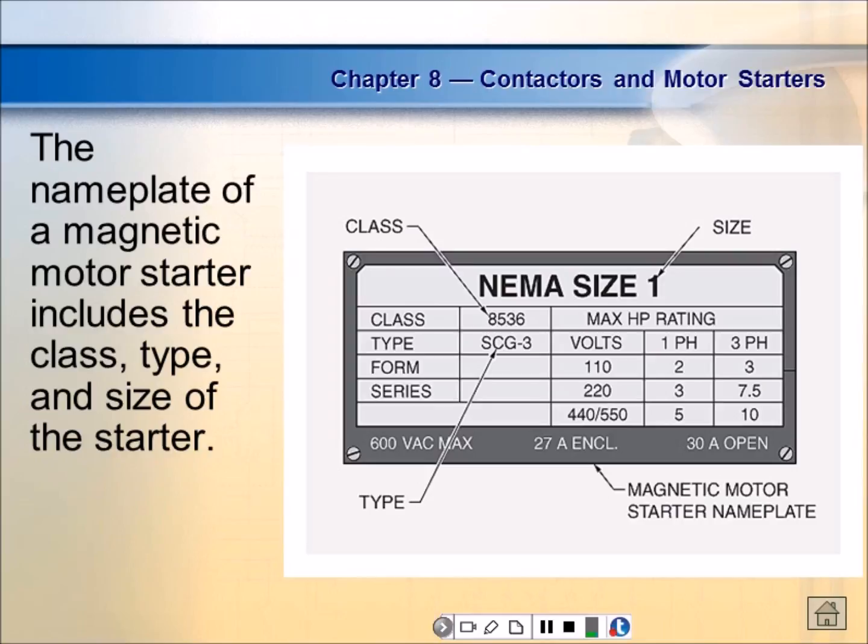Less current to run the motor. The motor doesn't produce more horsepower if you run it on high voltage, right? You understand? It's just going to draw less current to create that horsepower. And of course, you don't pay for current, you don't pay for voltage, you're paying for horsepower, or watts. Are we okay?